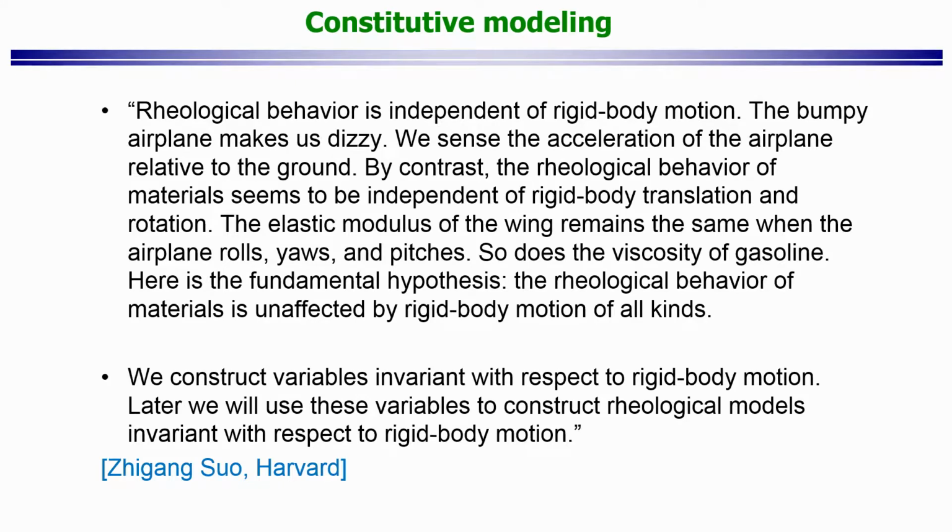The elastic modulus of the wing remains the same when the aeroplane rolls, yaws and pitches. So does the viscosity of gasoline. Here is the fundamental hypothesis. The rheological behavior of materials is unaffected by rigid body motion of all kinds. And then he goes on to say later that we construct variables invariant with respect to rigid body motion. Later we will use these variables to construct rheological models invariant with respect to rigid body motion.